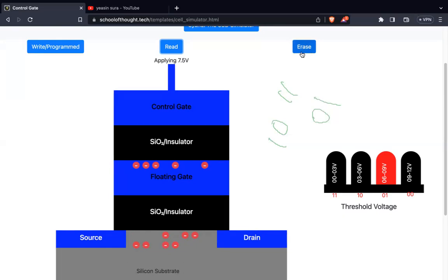Click on erase program. What happened? When electron started to flow from silicon substrate to the floating gate, some electrons got stuck in the insulator. When we click on erase button, some electron also gets stored, trapped in the insulator.